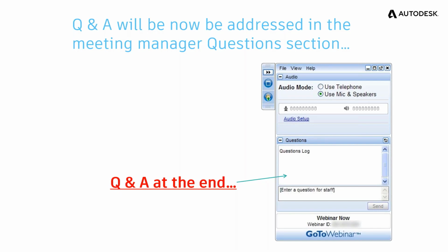When I delete the visibility state, what happens to the line work? Basically, they're asking when I delete a visibility state, what happens to the line work in that visibility state? If it was only showing up in that state, it's actually still in the block, and it's going to make the block quite large. You need to delete the line work first, and then the visibility state. Also, you need to make sure that line work's not appearing in another visibility state.